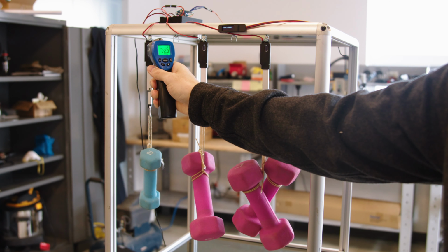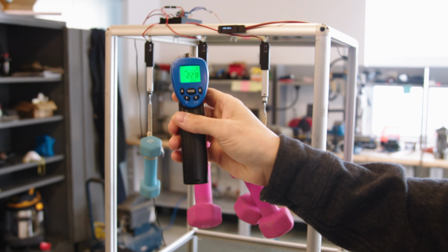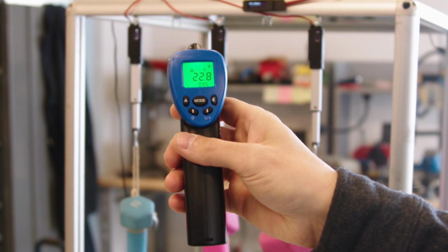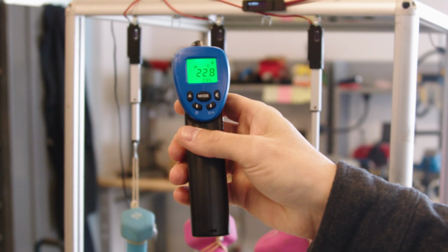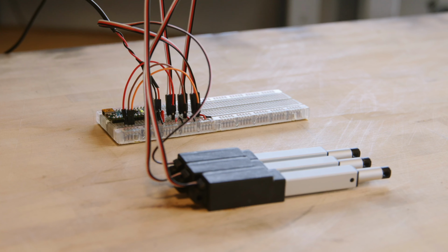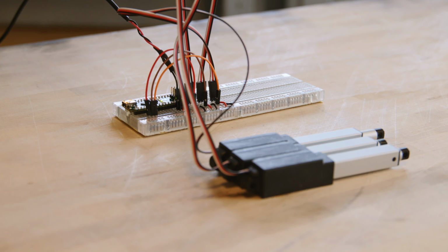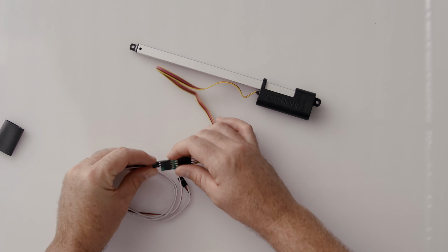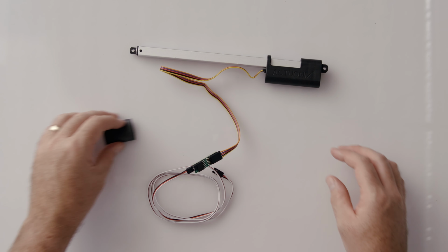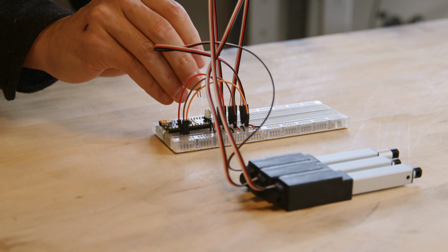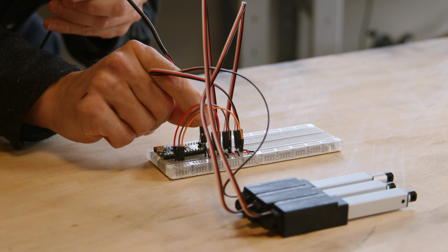This type of testing can help identify unexpected loading or other issues in the target application. Things like stall conditions, impacts and vibration, additional loading from friction, or binding in mechanisms and linkages. Sometimes this type of testing can be conducted using your application's own controller, but if this is difficult to implement or too early in the design process, using an Actuonics timer relay or controller may be a good way to perform this type of testing.